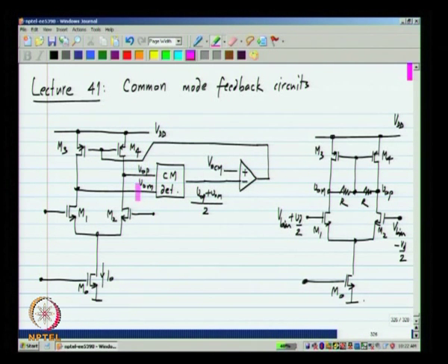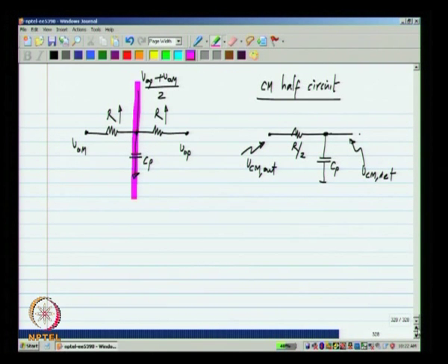But in any case, you know that a negative feedback system cannot have too many extra delays. So, here the transfer function from this point to that point would be a first order low pass transfer function. Okay. So, if R is very large, obviously the delay is very large, or the bandwidth of this low pass filter is very small. Okay.